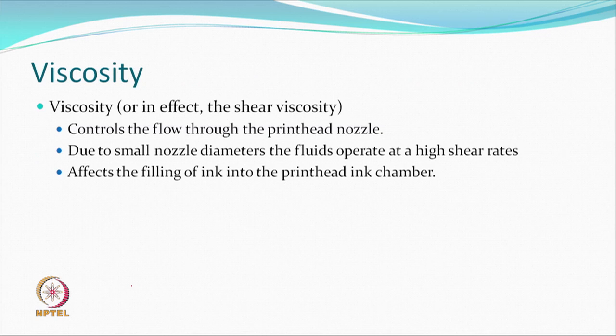Viscosity we just talked about before also. In effect, we are talking about the shear viscosity. So, it controls the flow through the print head nozzle. Due to small nozzle diameters, you can understand so many nozzles are there in a very small area. The fluid, while it is coming out, operates at higher shear rates. It affects the filling of the ink into the print head also. So, when it is coming out, it should have a high shear rate, but when it is stationary, then